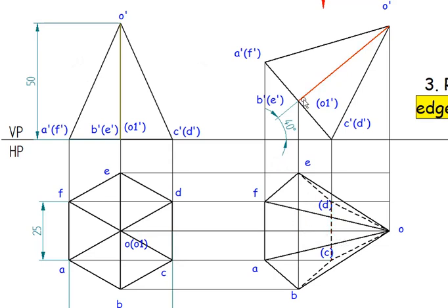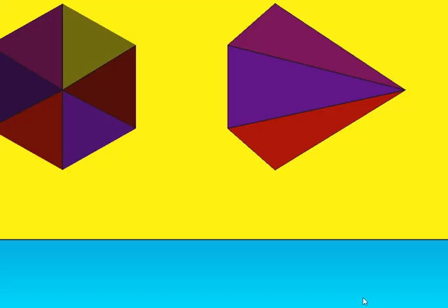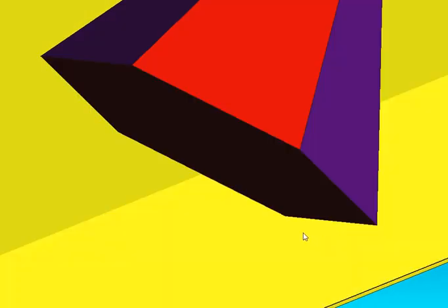So from here this should be the axis. So O1, you can see that O1 is nothing but comes under the base. O1 is not going to be visible. The farthest point is nothing but which is resting on HP. So even the base line joining this and this is not seen in the top view.